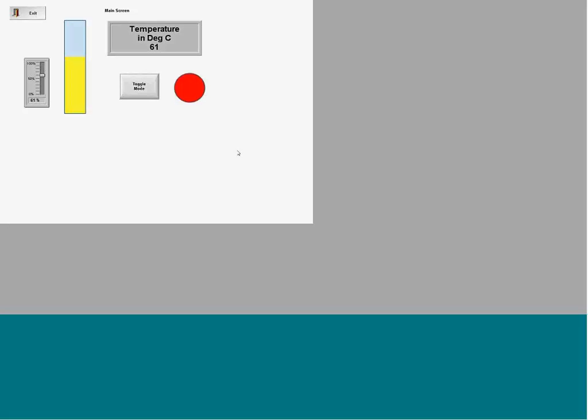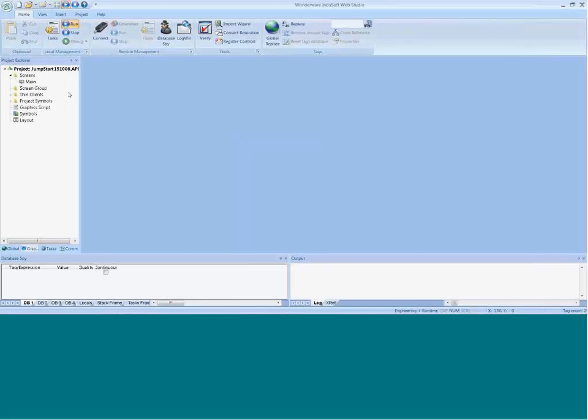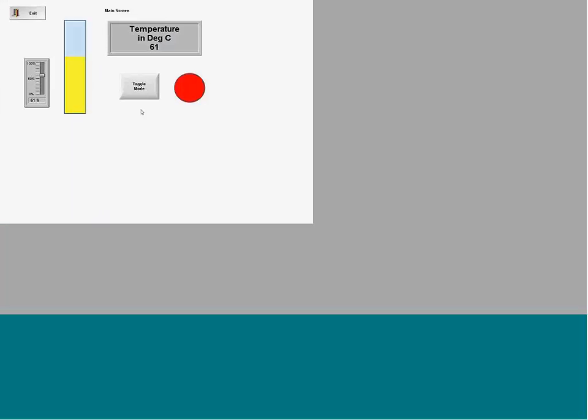If you didn't know this, and this is kind of important, about 10% of men are colorblind. So it's a good idea not to show status with only color changes, because about 10% of your operators aren't going to be able to see it anyway. So how do we get around this?